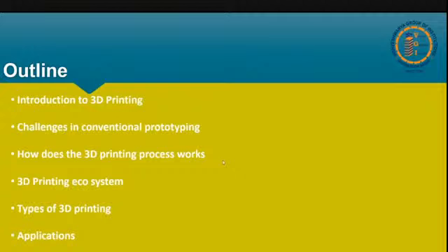There are basically two or three types of processes in the manufacturing space. The first is the formative process. Formative processes are like injection molding, casting, stamping, forging. Formative manufacturing typically forms material into the desired shape via heat or pressure.